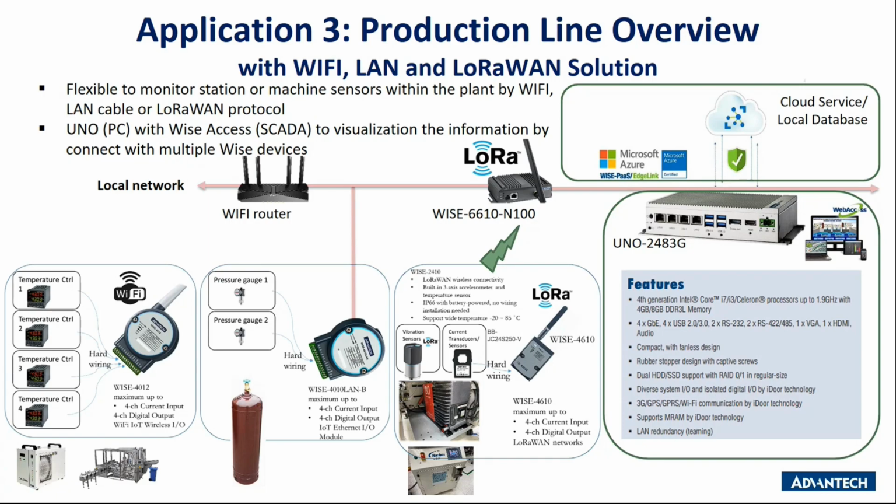And if let's say there's a further area and you want it monitored from our SCADA, LoRa will be another solution which is very suitable for our client. For example, if the client has a very wide space or a big plant, LoRa is very suitable.